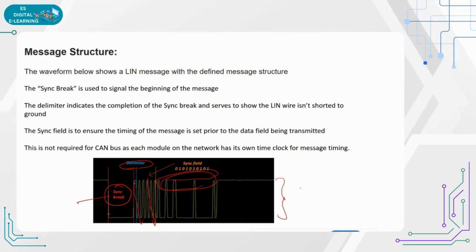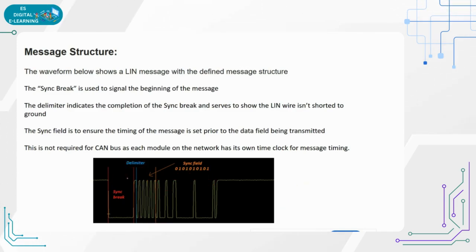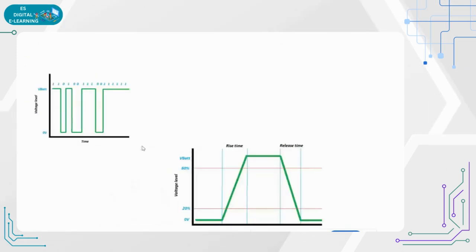Okay, so as I told you, in the oscilloscope we can see this information, how the messages are transmitting. And wherever you are seeing the peaks, the high peaks, those will be the ones, and the low bottoms will be the zeros. Like that, the data we are transmitting. It won't require a clock.